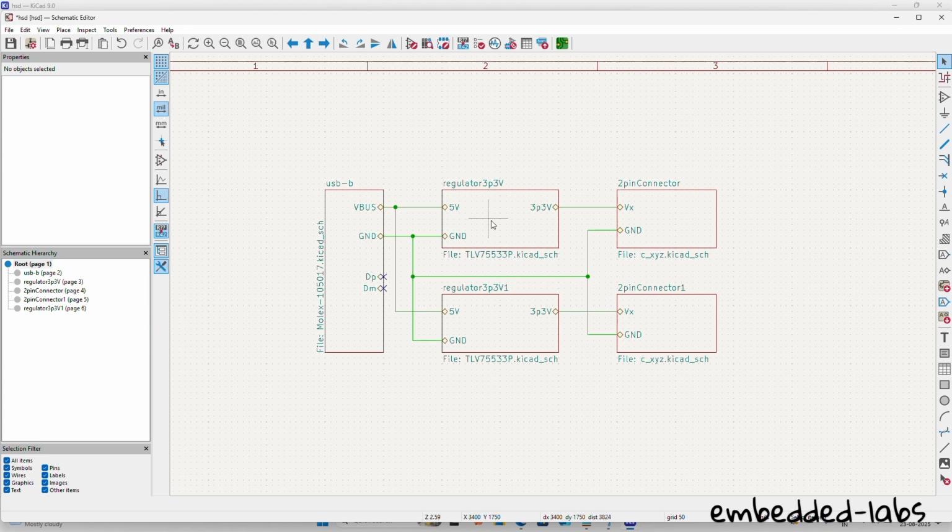So when you use a programming language which is designed in a hierarchical fashion, each of the files will have a scope. The variables in those files will have a scope and are not something that is accessed by a different block. So what goes inside this block remains inside that block. The labels remain inside that 3.3 volt. It is not visible to the other blocks. Only if you do the connections do these blocks get glued together.